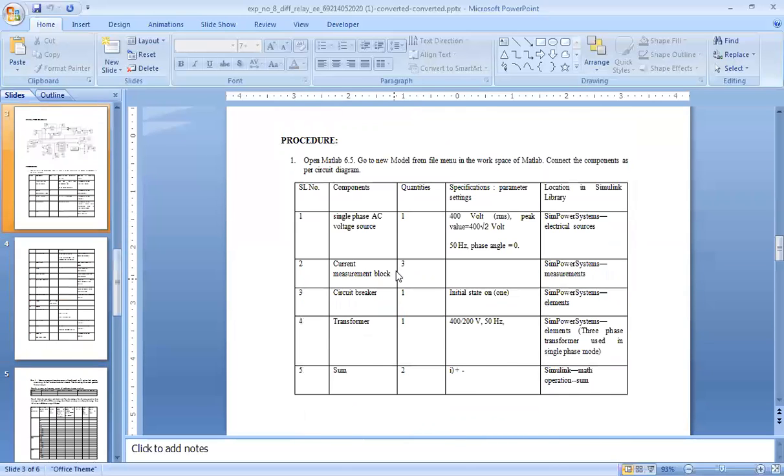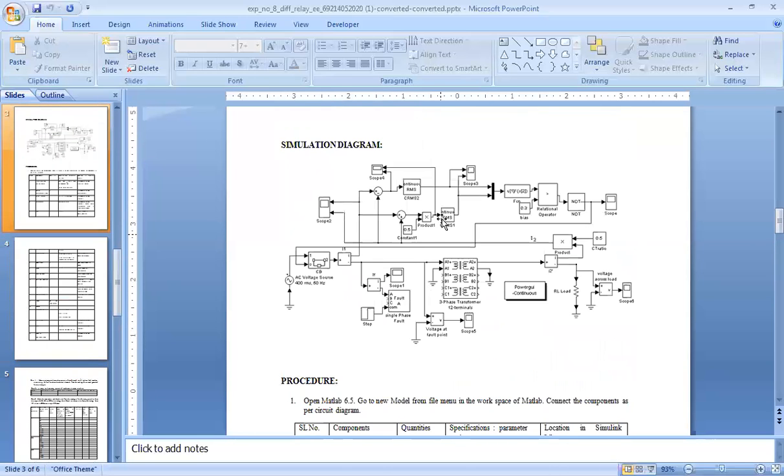One thing is very important, the RMS value. Here I have introduced two RMS blocks, that is continuous RMS, I1 minus I2. Before that it is not an RMS, it's a signal, and a signal cannot be divided by another signal. So we have to take the RMS value of this differential signal, and here we have to take the RMS value of this average signal.